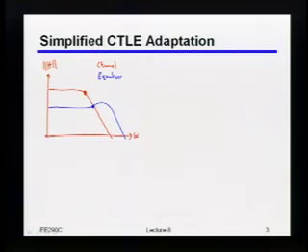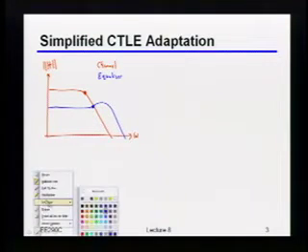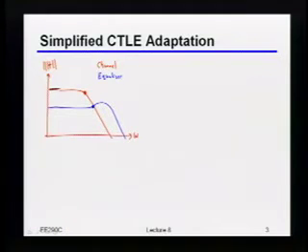So is the channel flat? No, it's not, right? So what is it going to look like? Just roughly. Yeah, I think Chintan kind of did it. Obviously down here it's flat. Then you hit the pole of the channel, then you hit the 0 of the equalizer. Actually, it'll be even faster than that because there are two poles there. It'll look something like this.